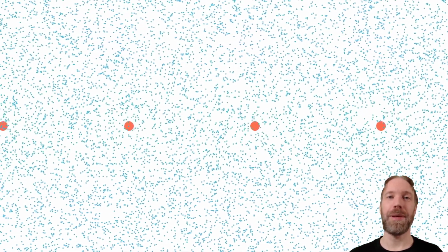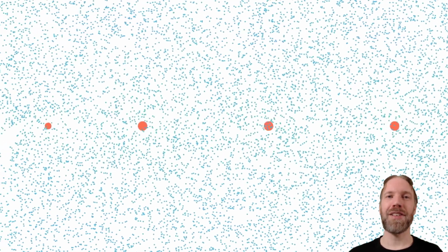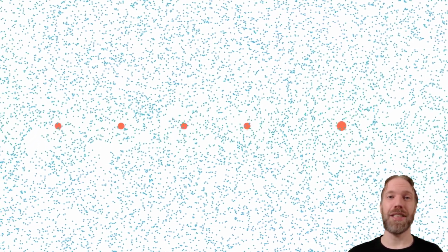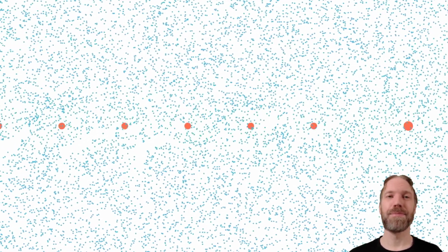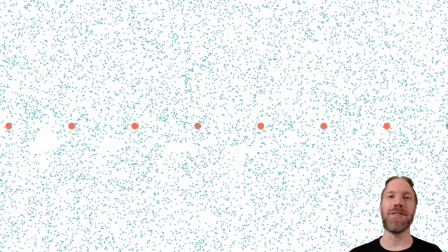In this illustration, the distance between the vortices will be decreased. At the same time, the strength of the vortices is reduced correspondingly. So when we have twice as many vortices, the strength is reduced to half to keep the average strength per length constant. For a wind turbine, this will correspond to adding twice as many blades and reducing the chord by half, hence keeping the average normal force constant.